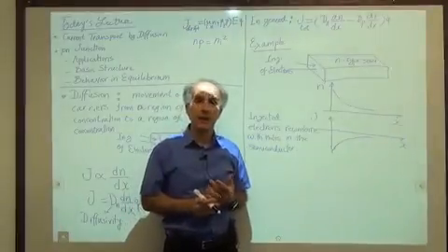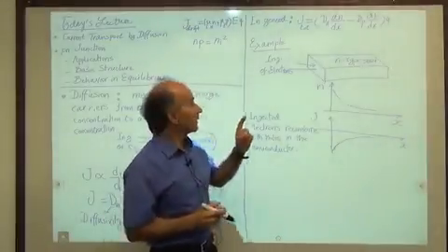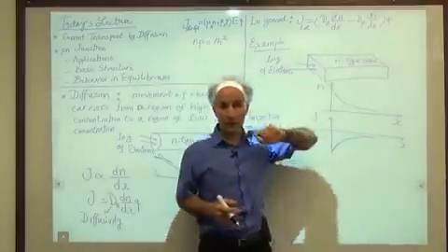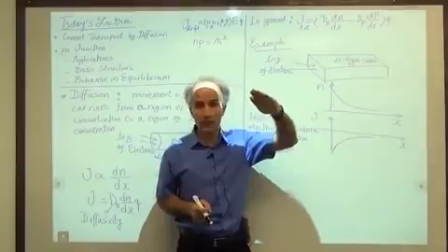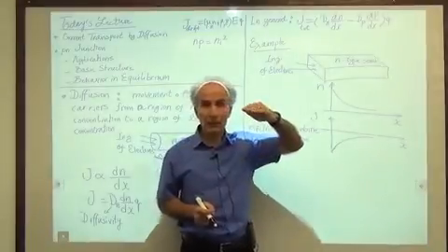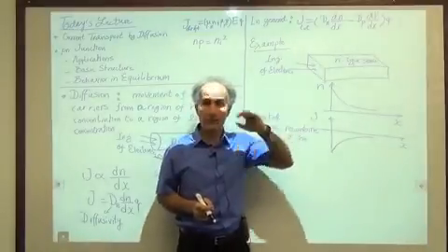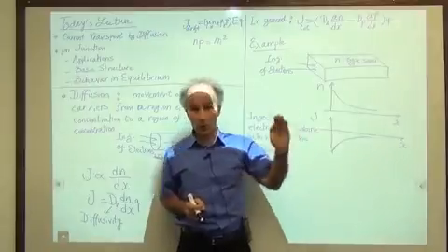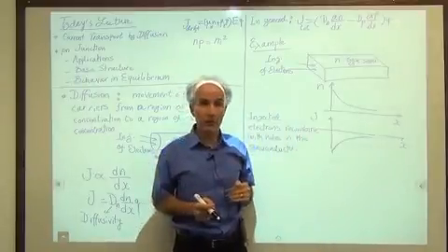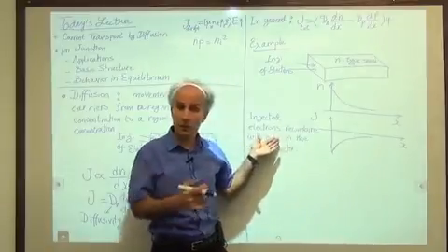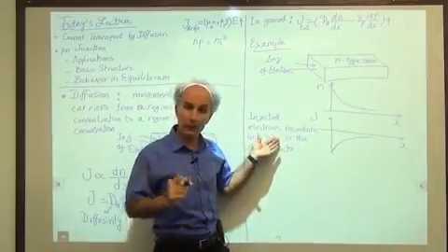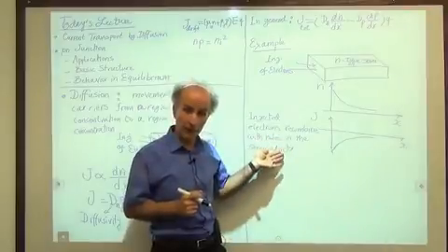Now you may say, well, I doped this semiconductor with a donor, with let's say phosphorus, so much that the number of holes available is very, very small, orders of magnitude smaller. So that shouldn't happen because we just don't have enough holes. We have very, very few holes for recombination.